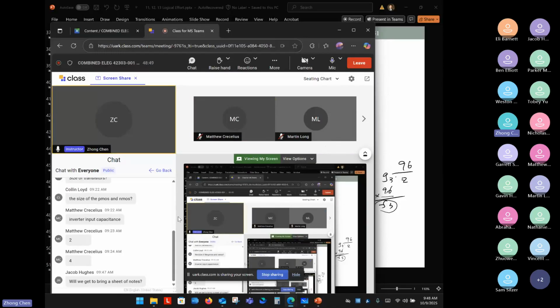What is the resistance on the P network? What is the capacitance associated with the P network? What is the output capacitance? And then you build that Elmore delay model. So you have the RC network, and then calculate the delay. It's going to be a little bit different. Once you calculate the total R and C, the final number will be something like 20 RC.